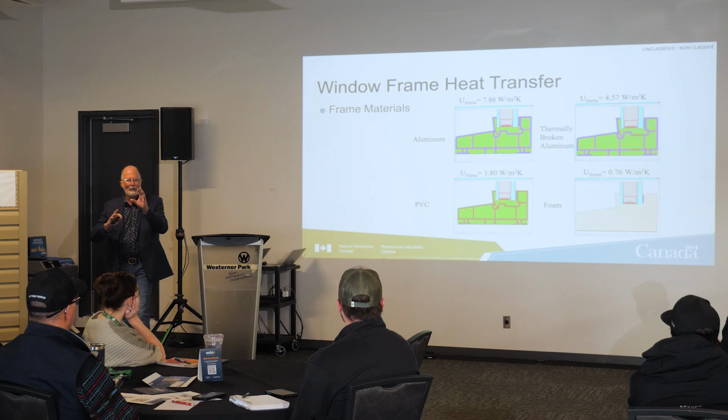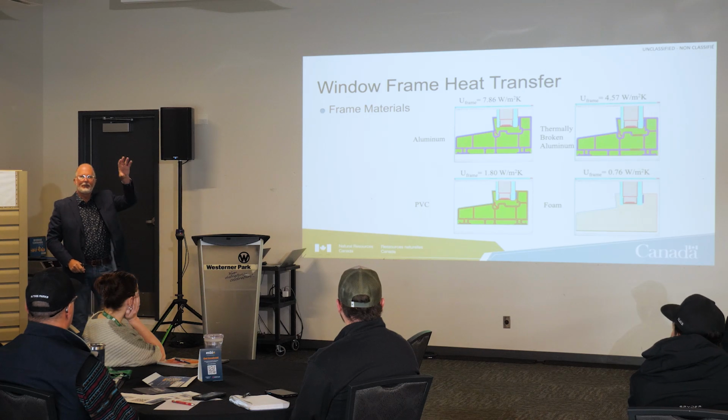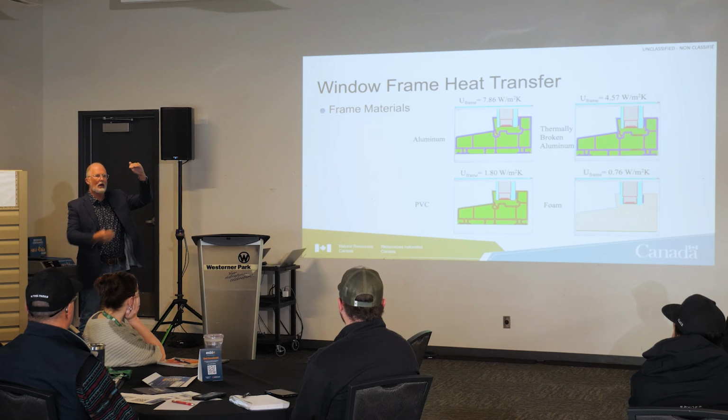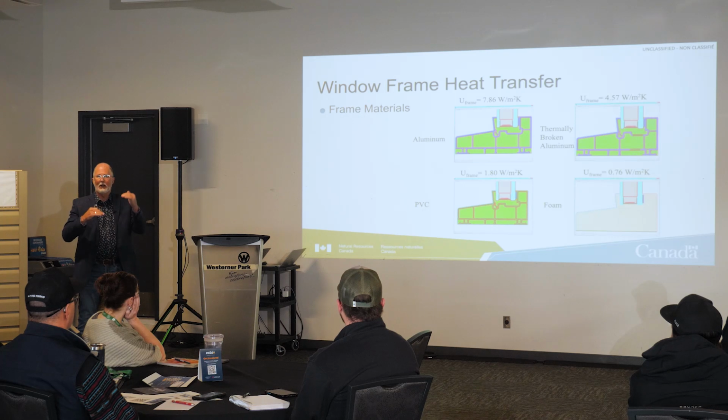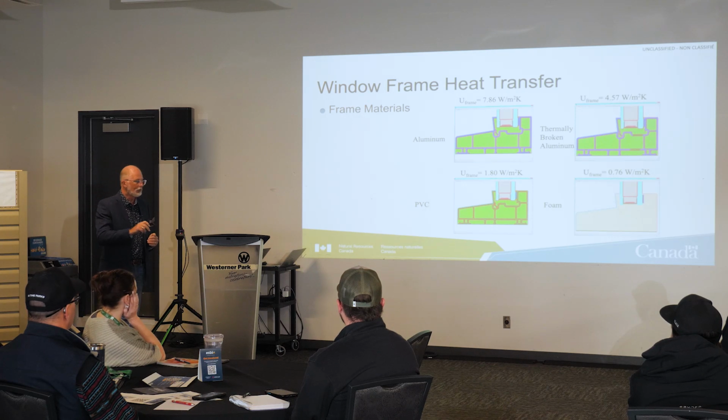So you can see what happens here. We have to get our window center of glass really, really high to offset if we're putting a window in like this, where it's a 1.8, because it's the overall average that our window is designed to.